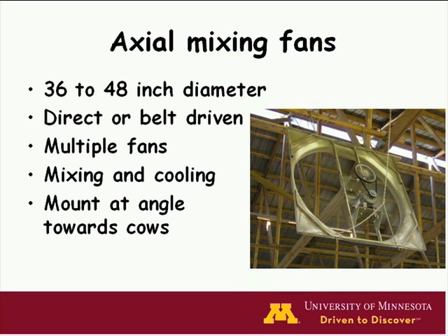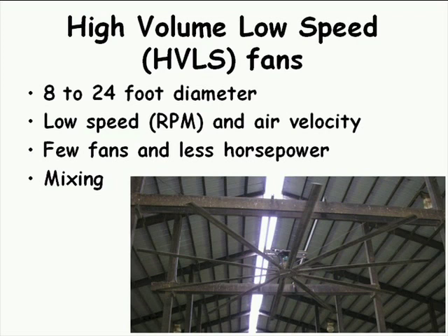A colleague a number of years ago visited a barn and was checking on the mixing fan performance and observed that they were mounted too vertically, and so it was just mixing the air above and not getting down at the cow level. So it's important to mount them with a bit of an angle so that they blow downwards towards the cows.